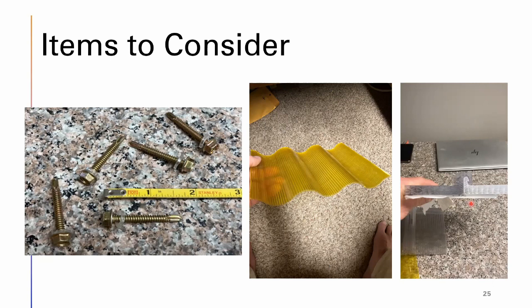Well, I get a longer growing season, but I don't grow as fast. I have a 71% transmissibility. Now, if I wanted to grow fast, I'd use the 2-layer, but the problem is I'd have a shorter growing season and then I'd have to supplement with heat. Olson's in Salem, they have about a $150,000 a year natural gas bill. Same thing up at Pinea in Ogden, about the same.